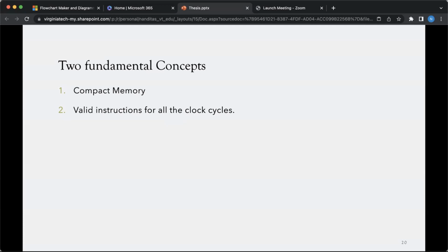So each test case is exploring the functional state of the processor. Which means that we will be giving it only and only valid scenarios, and we will constrain our instructions in a way that every time it lands on an instruction memory where it is getting a valid instruction and not some random value, so that it does not go into an exception state.